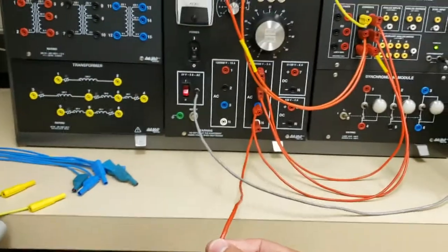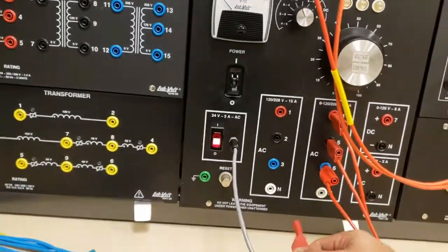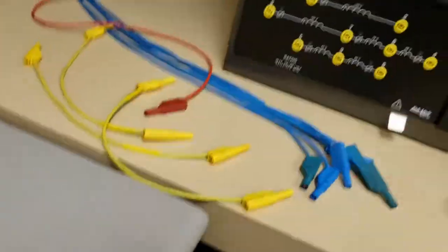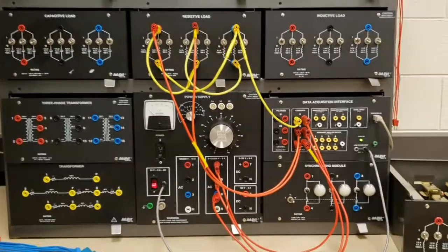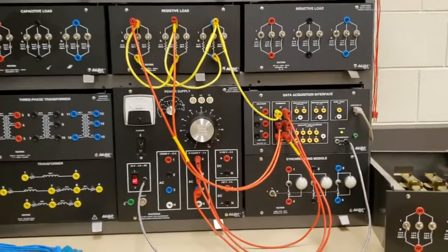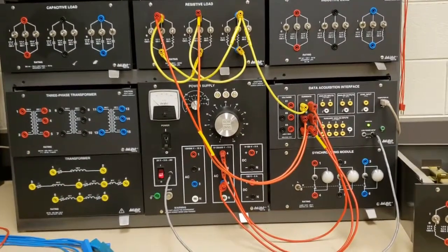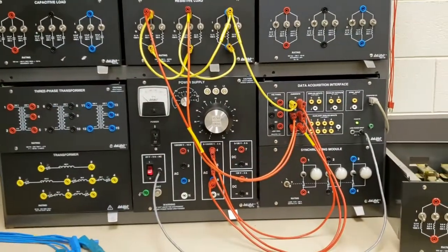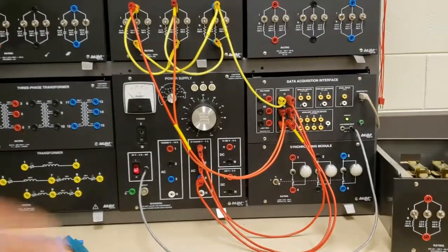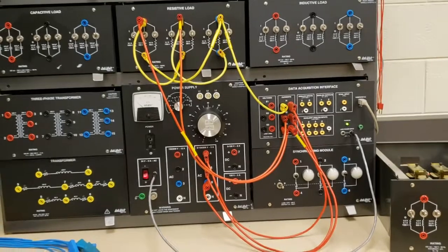And if I did, you'll find there's this neutral line that used to be there with the Y configured load. I can remove that now because delta configured loads do not have a neutral line. So actually there is a benefit to delta systems. Just on this basis, they require fewer wires. And you'll see that there are actually other benefits from delta configured loads. Some of you might not feel like there is much of a benefit, and they're a little bit more complicated and weird to analyze. But trust me, there are benefits.